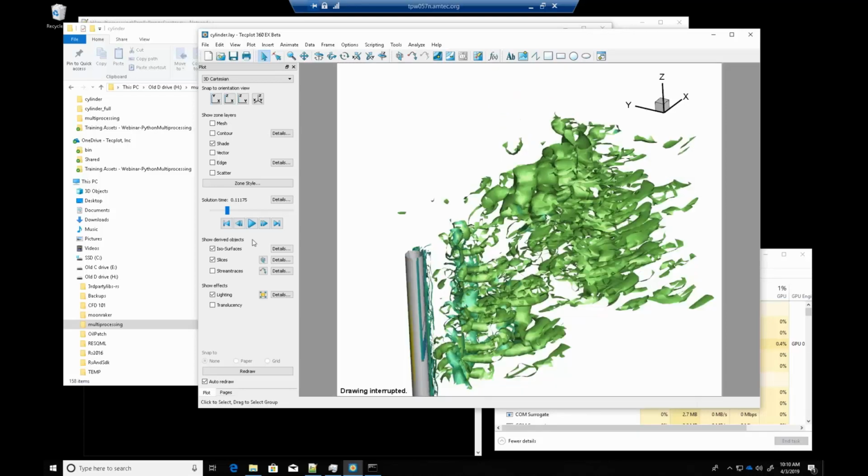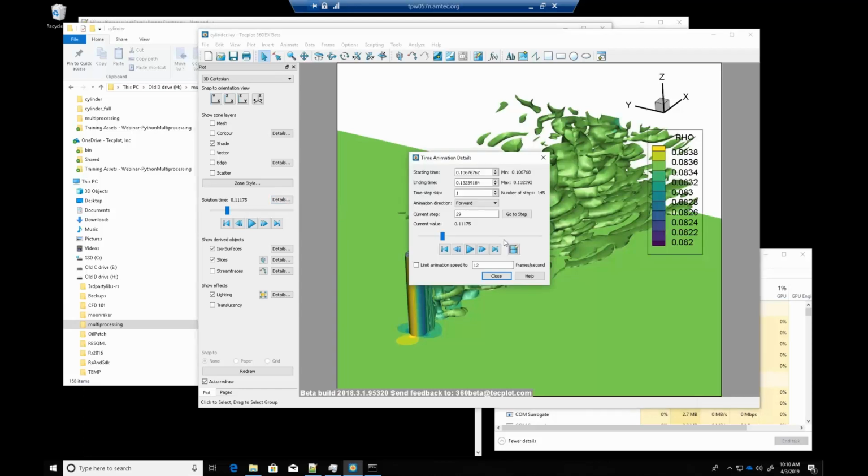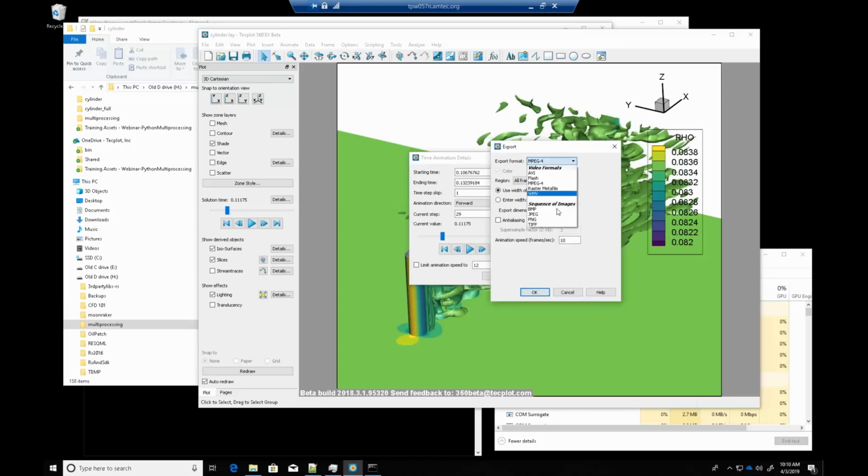So before we get into the Python side of things, let me go into Tecplot really quickly about animating to files or animating to images. One of the new capabilities that we've added in the 2018 R2 release is the ability to export to a sequence of images. This is really nice because you can take these images and combine them into a movie. You can combine them into movie file formats that we don't necessarily support. We have some users who need to do GIF, and they're able to use a tool like ImageMagick to create animated GIF. So this is a nice little addition.